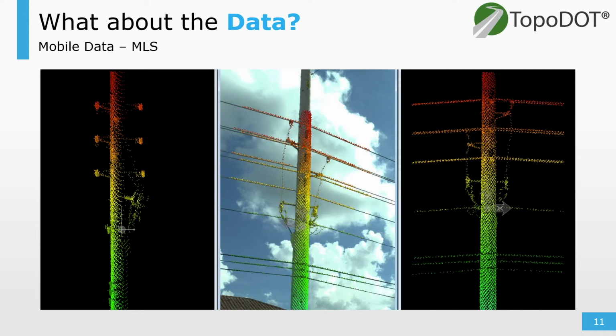What we're looking at here is a mobile data set from a Regal mobile system. This is a dual head scanner configuration, which is going to give us plenty of detail. And keep in mind, this is from a single pass only. So if it doesn't necessarily need control, especially if we're doing a bunch of relative measurements, it just cuts down on registration time too. But with that single pass, we have all this information.